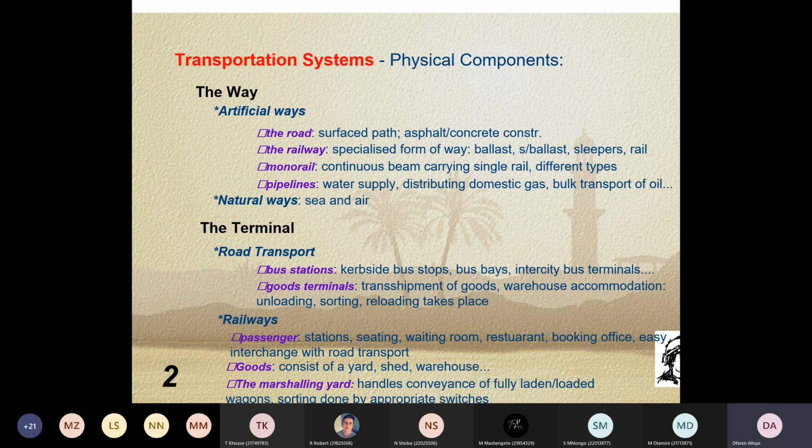Depending on the capacity, what we refer to as the carrying capacity of the in situ material, it may not be strong enough to build your asphalt pavement above it. So you have what we call superimposed layers. You could have a selected subgrade, you could have a sub-base layer, a base layer, and then your surfacing above it, your asphalt above it.